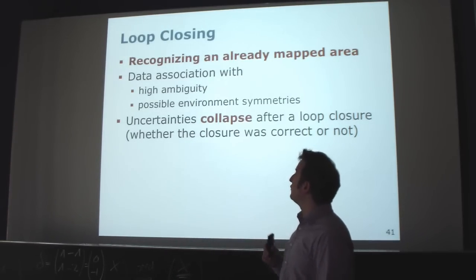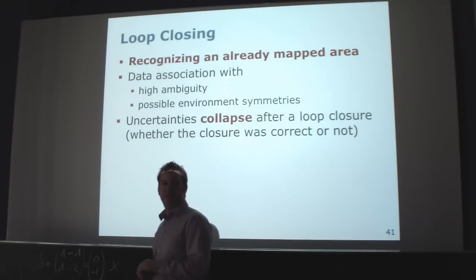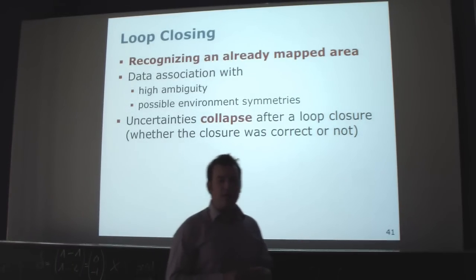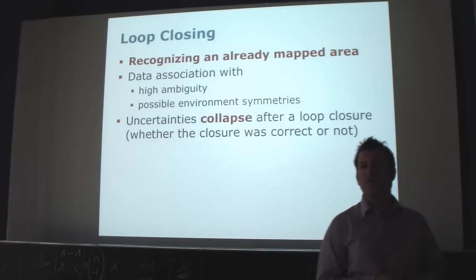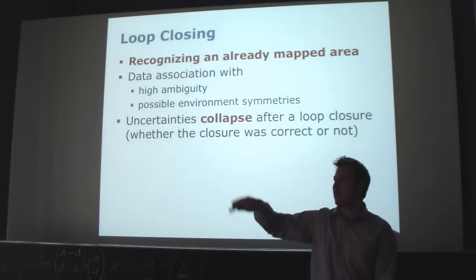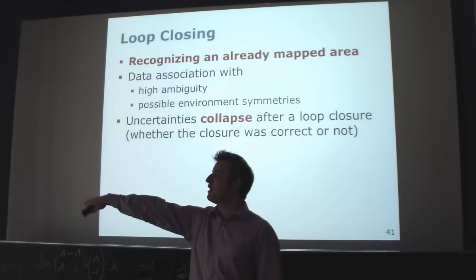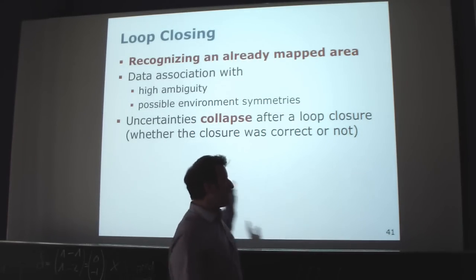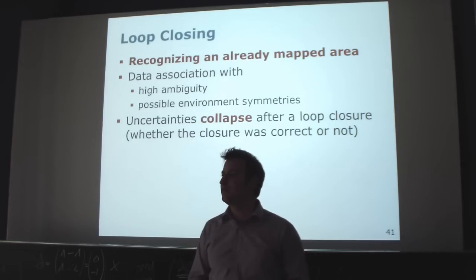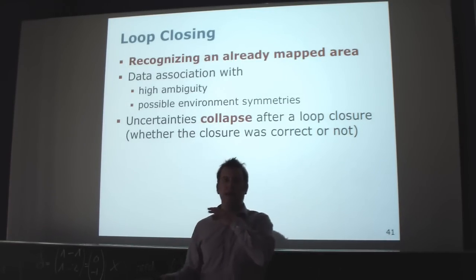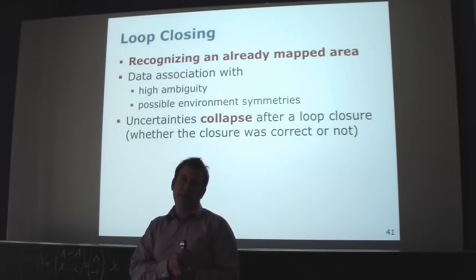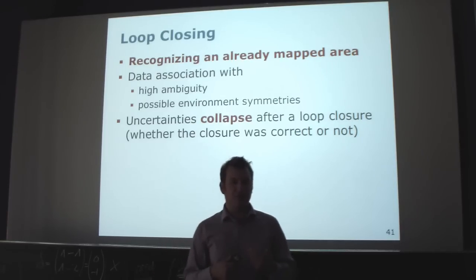The first thing, which is important not only to EKF SLAM but to SLAM in general, is what we call loop closing. Loop closing means recognizing an area where the robot has been before and returns to. So you drive around here on campus, let's say you nicely map this area in front of the building, you move around the building, and re-enter this area here from the George Köhler Allee. So you will re-enter an already mapped place. You have to make this association: where am I given the model I built so far? And this is what we call loop closing.